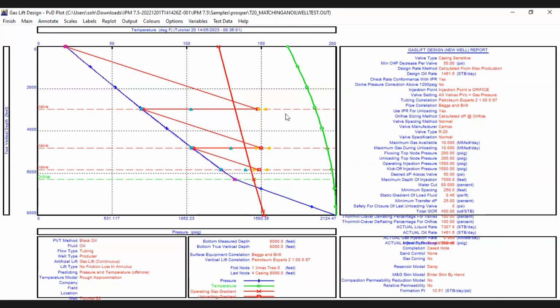Listen carefully. In the gas lift design, P minimum represents the minimum pressure drop that can be achieved at a specific depth in a well during the unloading process when gas is injected at the defined depth. The pressure drop occurs when gas is injected into the wellbore, which reduces the hydrostatic pressure of the liquid column and helps lift the liquid to the surface. P minimum is important because it helps engineers determine the minimum gas pressure needed to lift the liquid at that depth.